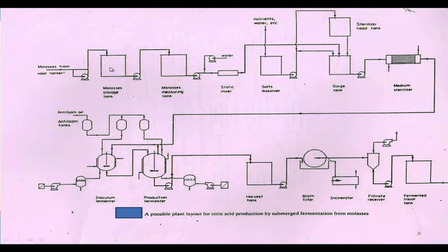But we observed we have acute scarcity. In the off season we have an acute scarcity of cane molasses, because in India cane molasses is also used largely for ethanol production. So we replace the cane molasses by using hydrol. Hydrol is a byproduct of the glucose industry. After crystallization of glucose, the mother liquor contains about 50% sugar, so it is used to replace the molasses. So we successfully replaced a portion of the cane molasses during the off season, and we found it suitable for